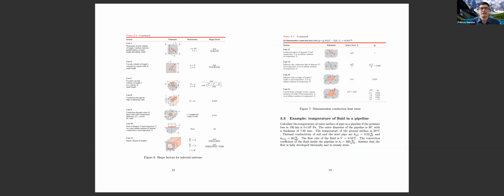Let's start with this. Where does the heat of the pipeline come from? Because nobody heats up the fluid, right? I know that in the oil sands, sometimes we heat it to make it more fluid. But what happens in pipelines is the frictional loss. The pressure losses are energy that is transformed into heat, and that heat is what heats up the fluid. Now, that heat doesn't accumulate forever. That heat actually flows through the soil to the surface. And this is what the problem is about.